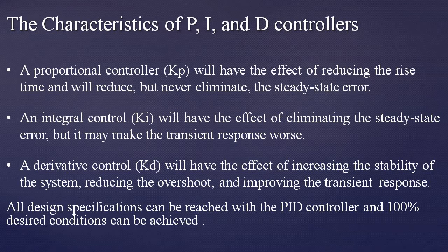Integral control will have the effect of eliminating the steady state error, but it may make the transient response worse. Derivative control, that is KD, will have the effect of increasing the stability of the system, reducing the overshoot and improving the transient response. Now all design specifications can be reached with the PID controller and the 100% desired condition can be achieved.